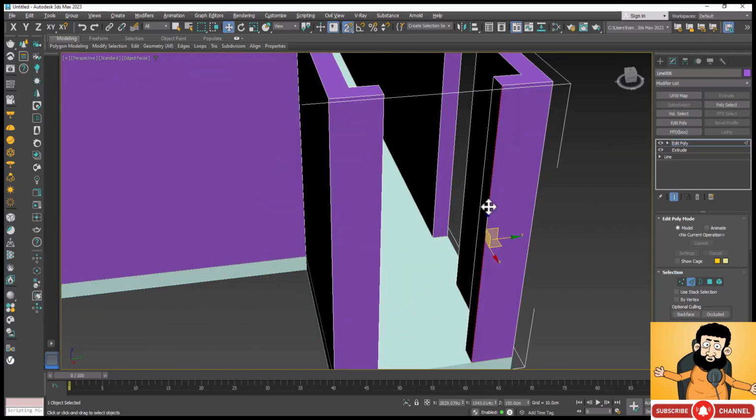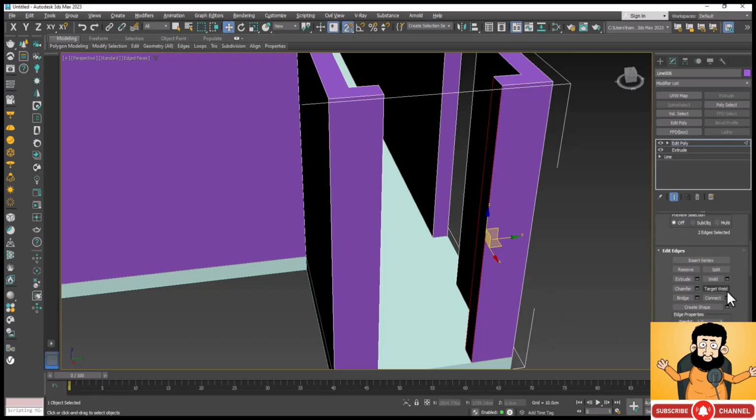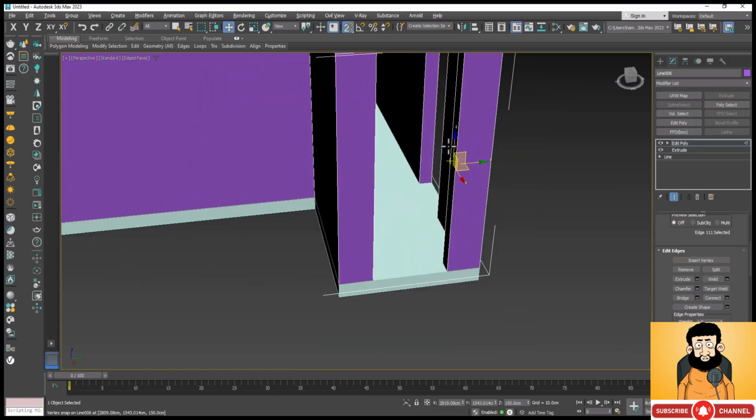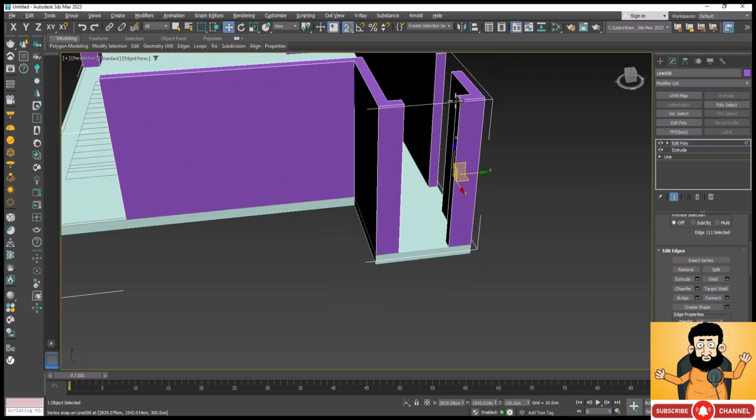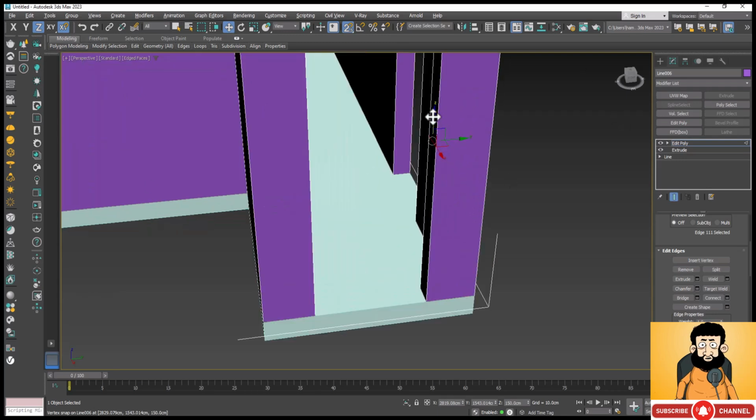I'll select 2 edges of my wall, select one, and now I want to select the next one. See, this is cleared from the selection, and then we hold the control, so that they are selected anyway. I'll come and give them a connect. So we want a connect, okay, and I'll bring this connection. We can give it a number from above, and I'll bring it from below. Sorry, why did it happen like this? Because our axis was not active here. I'll activate it on the z-axis. Sorry, it was locked. I'll take it from the z-axis in this.